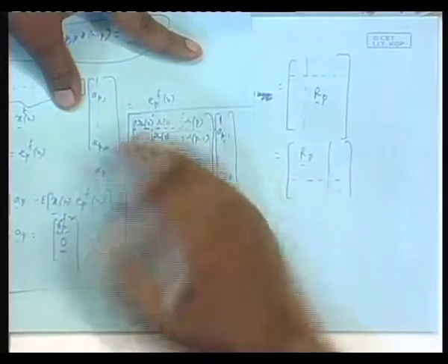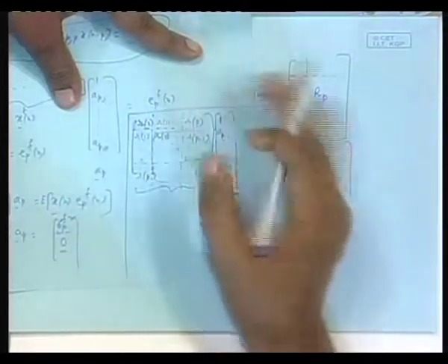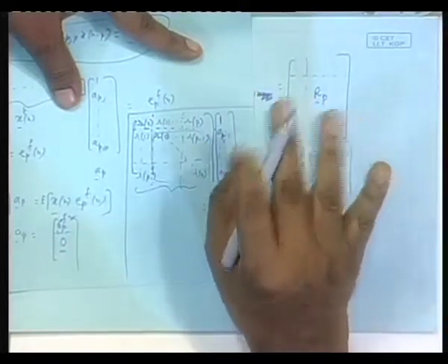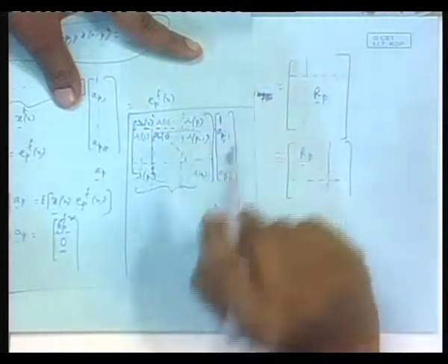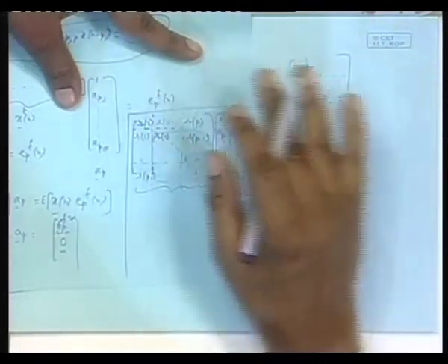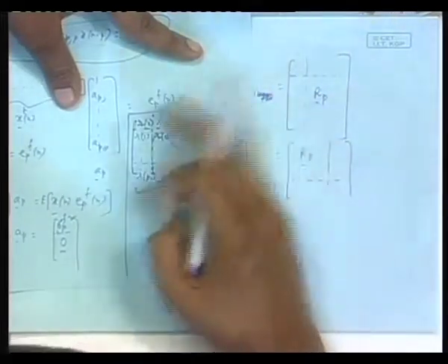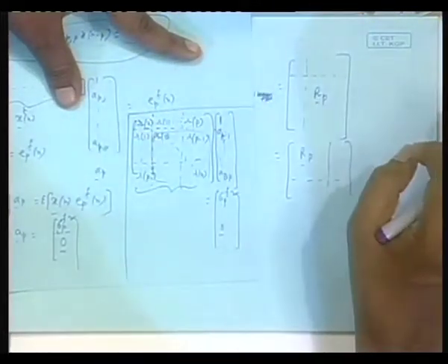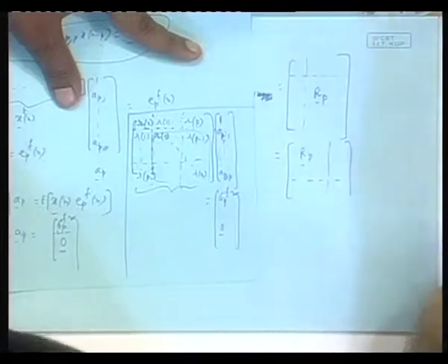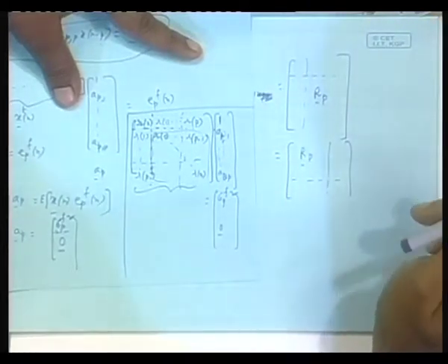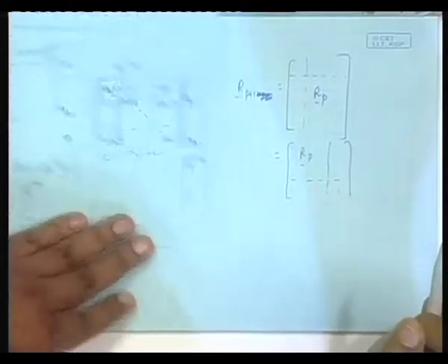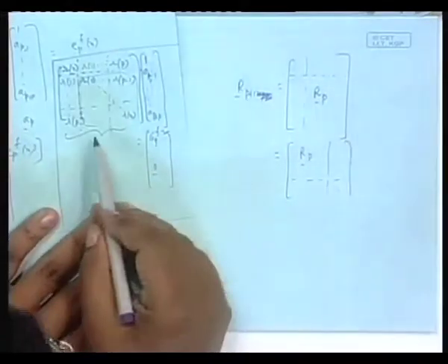On top of it, it is also symmetric, though symmetry is not really needed very much here. In the non-symmetric case also I can apply Levinson-Durbin recursion. In fact, it is done in the AR estimation part of the ARMA modeling problem, where the matrix is not symmetric but Toeplitz, and that is enough for Levinson-Durbin to work. The way they go about it is this: you are solving an equation like this.